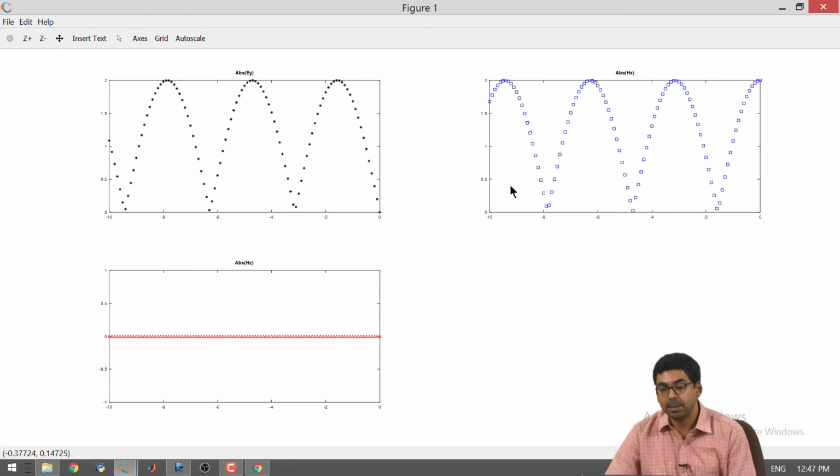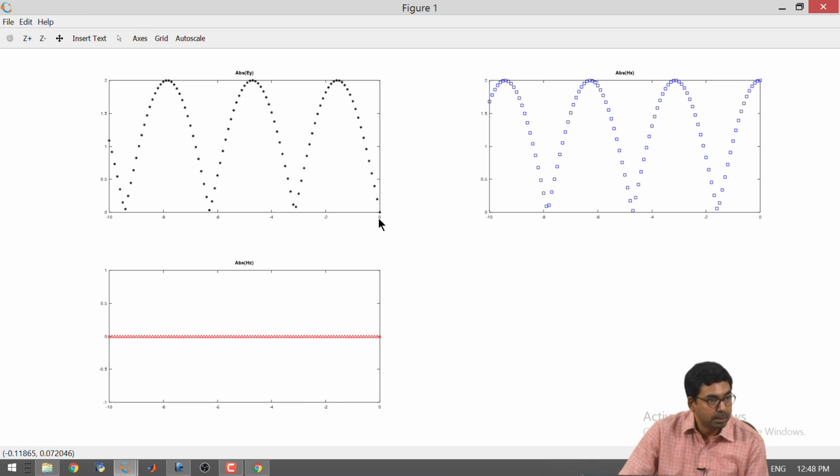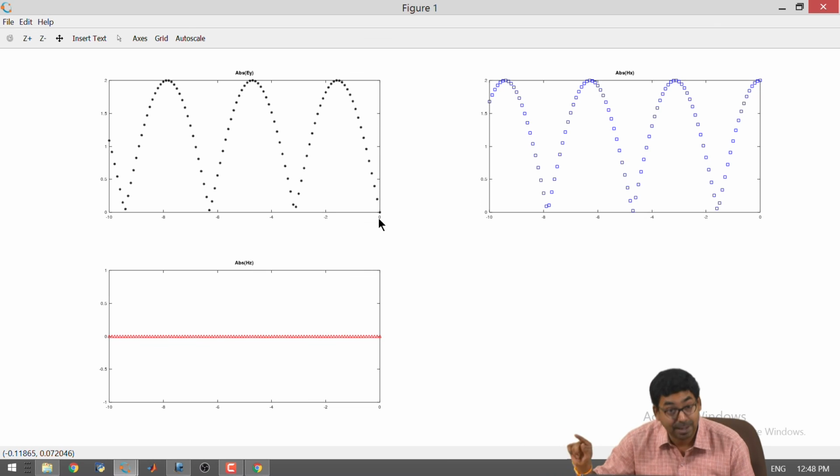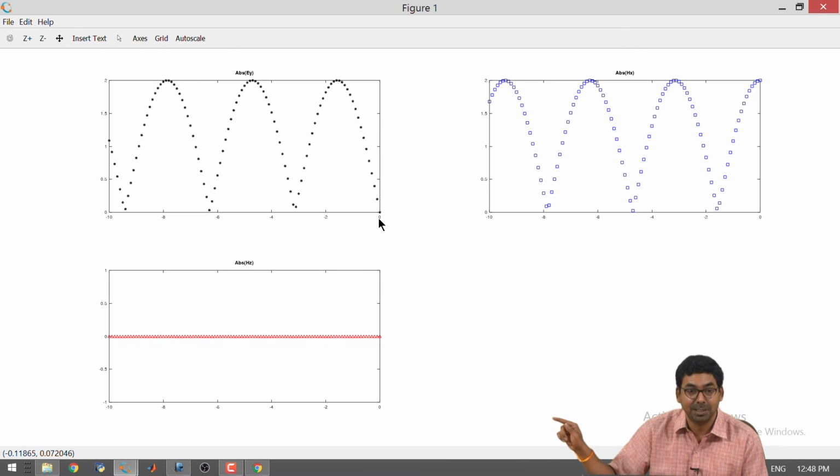The other thing that we notice is Hx is maximum at the interface. Ey is minimum at the interface. One can always calculate a Poynting vector, and I can say that in this case I will take Ey crossed with Hx, and I will get that the net power, because I am having y cross x, I am having net power in z direction will be 0.